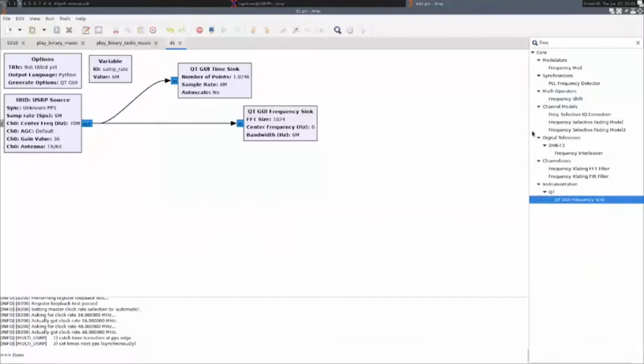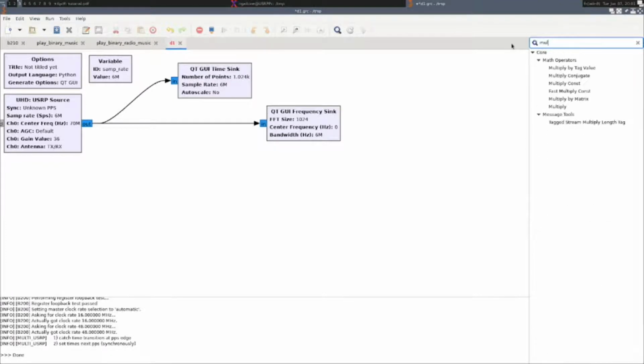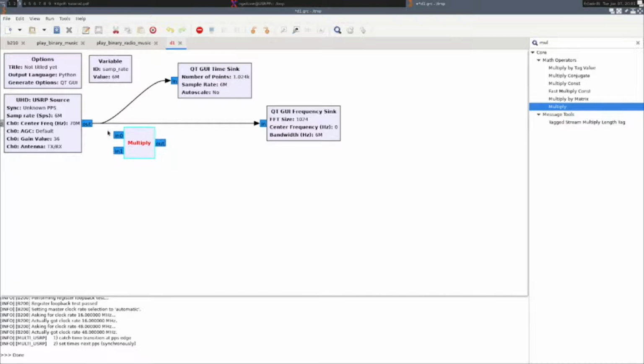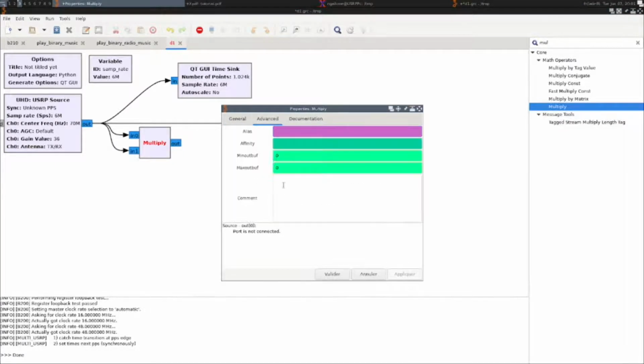So the objective of the demodulation is to try to identify the carrier, and a classical way of identifying a carrier is to square the signal. Indeed, if you have a binary phase shift keying, so with a phase of 0 or pi, by squaring the signal, we're going to create something that is, from 0 or pi state, we're going to square this, and by squaring the argument we get something which is 0 or 2 pi, and 2 pi is 0 radians.